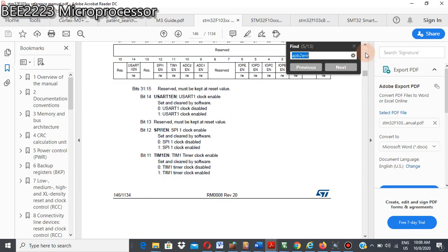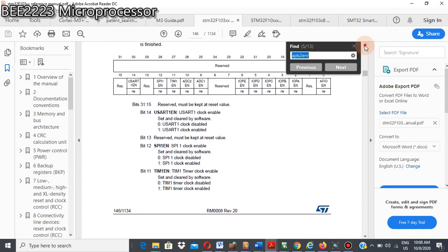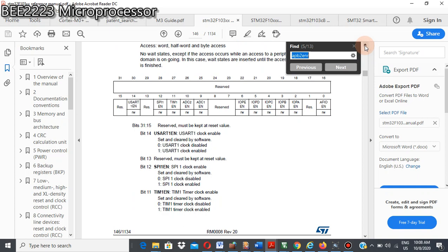So if we want to activate or power up these two ports, both bits, we need to write logic 1. So the value that we need to write here is 1100, equivalent to C, and all the other bits are 0, 0000, 0C.